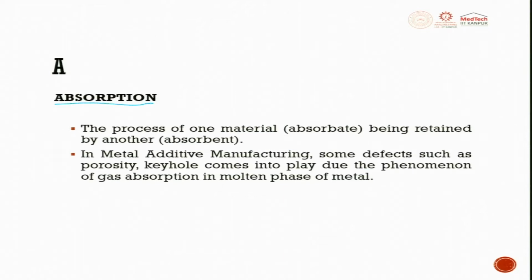The word itself clearly says absorb, adsorption, the process of one material being retained by another. In metal additive manufacturing, some defects such as porosity and keyhole come into play due to the phenomenon of gas absorption in the molten phase of metal.